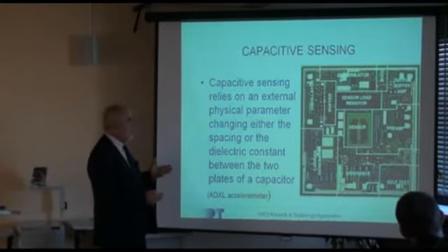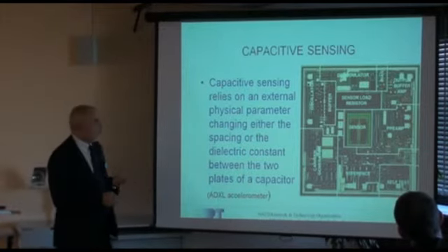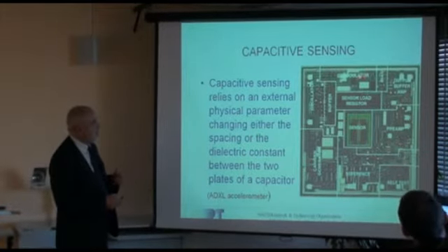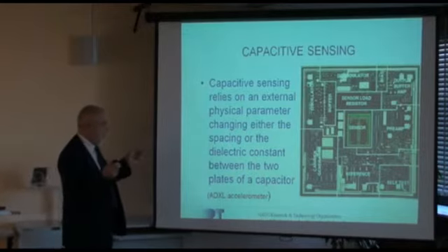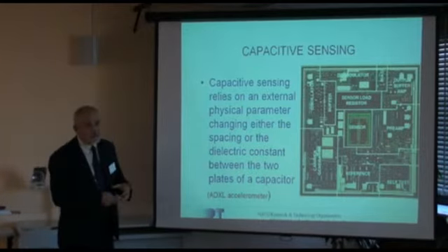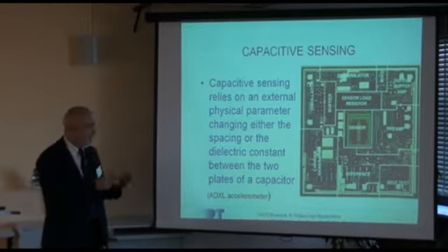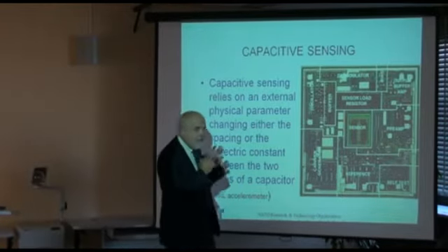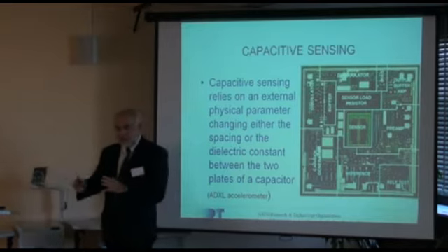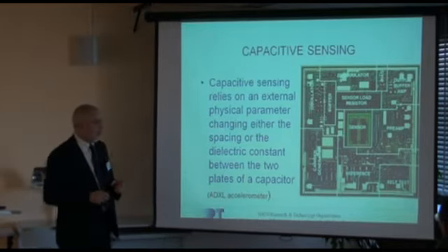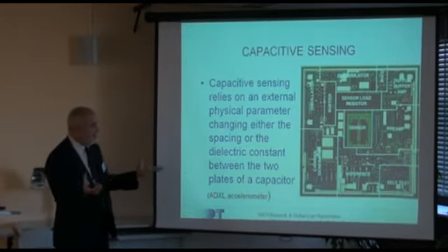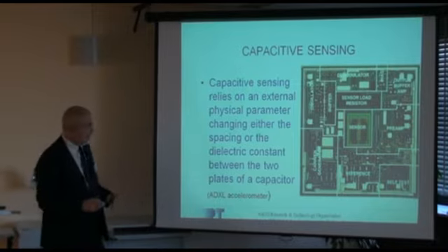We have the overload for the charge. We have modulator, demodulator. We have reference, self-test. We have preamplifier. We have all the electronics on the chip. It's built such that in one single run of the technology, you get everything on the chip. Basically, when you take it out, you just package and sell it, right?